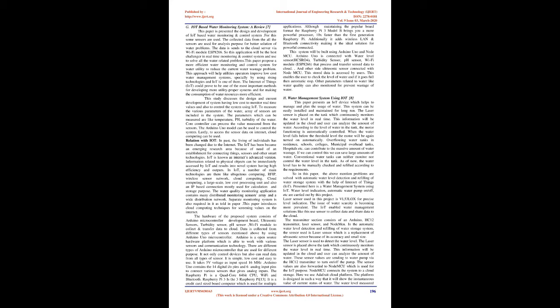The motor is used to fill the empty tank. If the tank level is below 10%, then the motor automatically gets on, and if the tank level is greater than 80%, then it gets off. The relay is used to control the functioning of the motor. Relays are switches that open and close circuits electromechanically. A relay controls one electrical circuit by opening and closing contacts in another circuit.